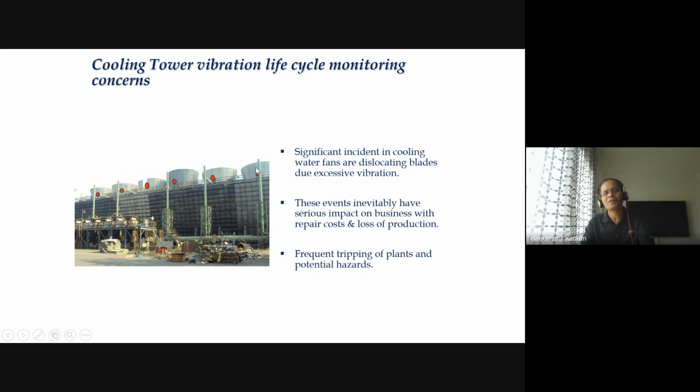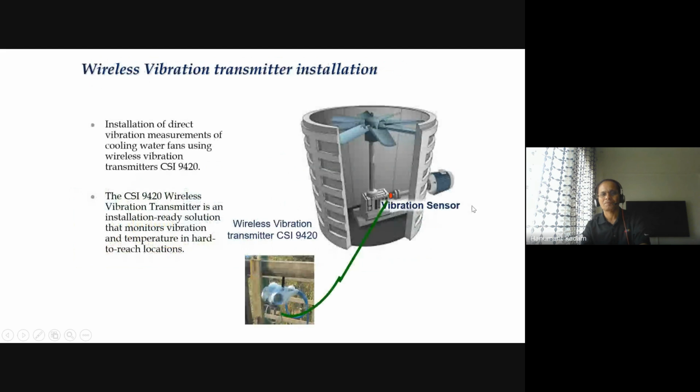There are vibration sensors, but whether they are working or have any problem, that was the issue. So the basic principle you can see here. This is the way it acts. This is what you have seen, one of the vibration towers. This is the fan I was talking about, and the blade gets dislocated. These blades, due to the excessive vibrations. And you see this motor, and this is a rotor.